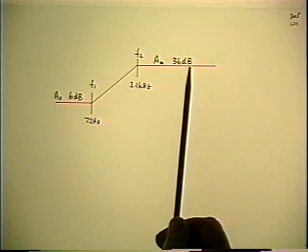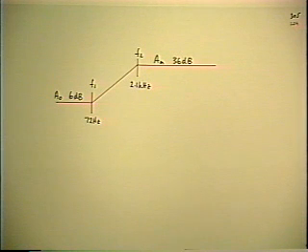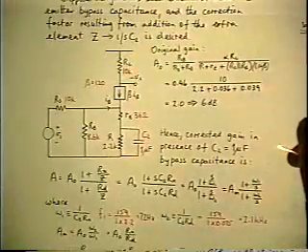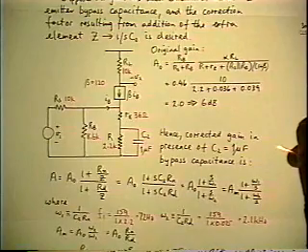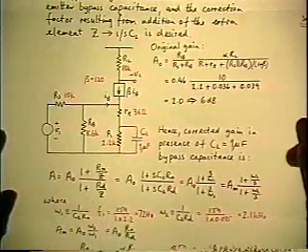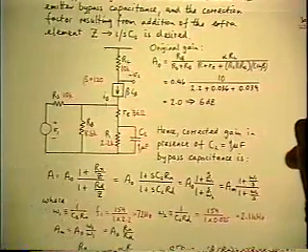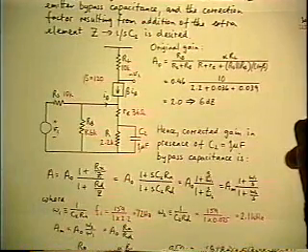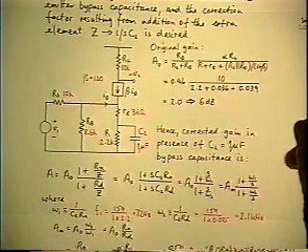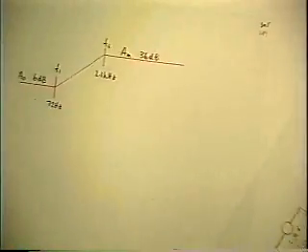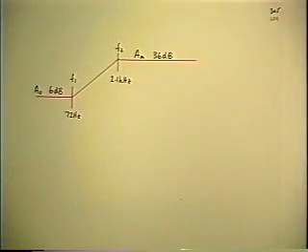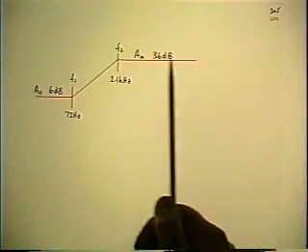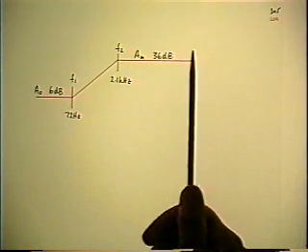In a typical application, of course, the mid-band gain is probably the one which is most relevant to the specification, and the bypass capacitor there is simply to eliminate the effect of the R as far as the main gain and frequency response is concerned. So the high value of gain that you get is the one that you have to meet the specification with.